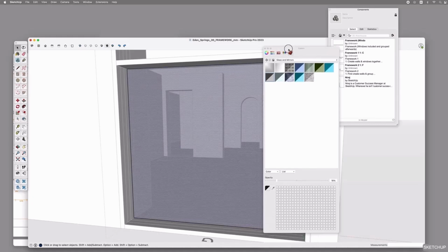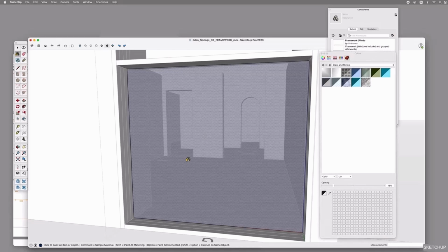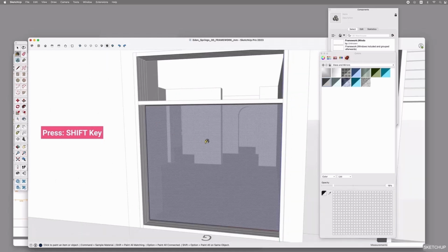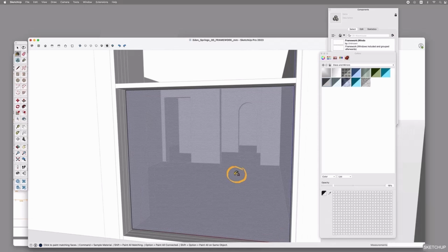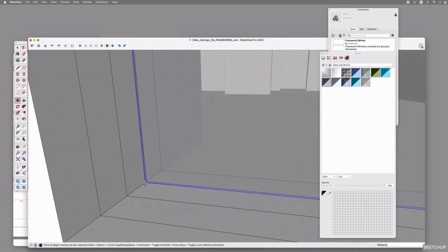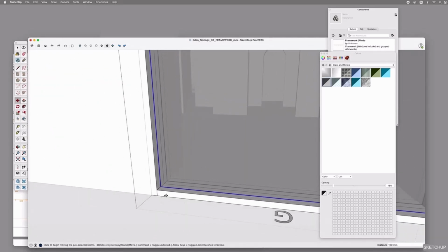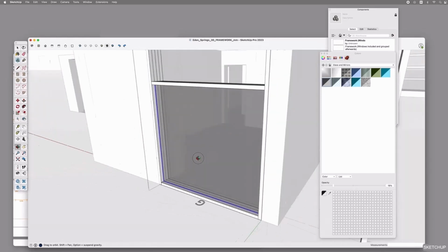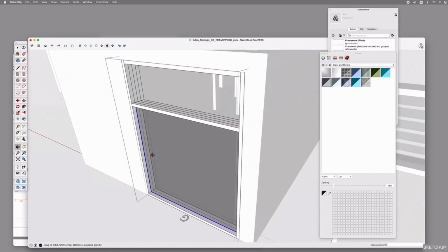And instead of having to colorate each surface by itself, there's an easy trick. If you press the Shift key, you can see 3 little squares appearing. This means that SketchUp will apply the whole material on all surfaces within this group. We can then leave the group and copy this panel again if we would like to have a double glass window front. You don't have to work with 2 panels. If you just need 1 panel, that's fine too. It's up to you on how you construct your windows. I choose this only for you to see some more features.